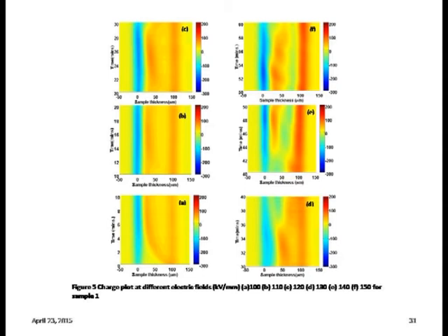So this is the thickness, and this 0 is for the ground electrode, this 100 is for the high voltage electrode. So here the color difference means the charge is negative here, and red color means charge is positive here. This is minus 300 to 200 you can see. Now you can see here some charge is coming like this and getting accumulated here, and this is 0 to 10 minutes, 10 to 20 minutes. Actually we cannot plot continuously due to the limitation of software. So this is continuous only with RAM. Up to 30 minutes we have done the experiment.